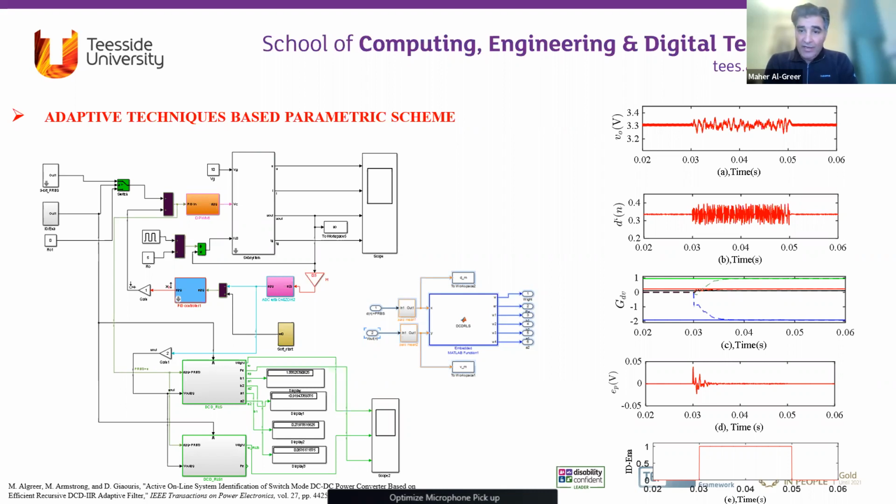However, the good point is that recursive and estimation techniques become more excited and richer in frequency and detail when there is some noise in the system. That will help the algorithms with the estimation, and the convergence rate will be increased. However, this should be considered in the model structure. I mentioned, when explaining the differences between non-parametric and parametric techniques, that we need to select the right model to estimate the unknown system. So this is maybe the weak point of parametric techniques. If there is any uncertainty or other disturbances, that should be included. And that's why there are different structures of modeling, which I haven't gone through in detail, that can consider uncertainties in the system.